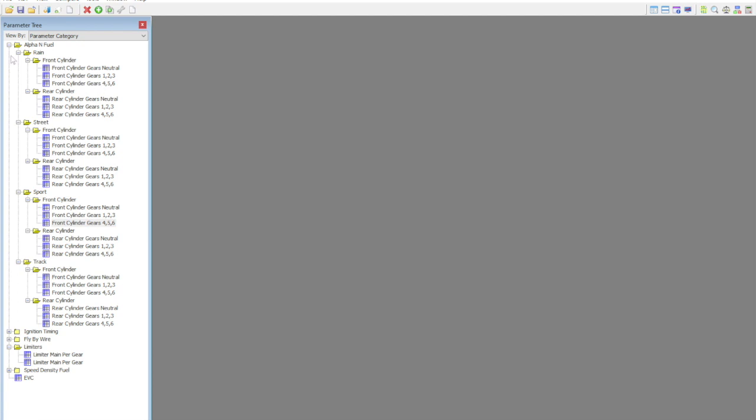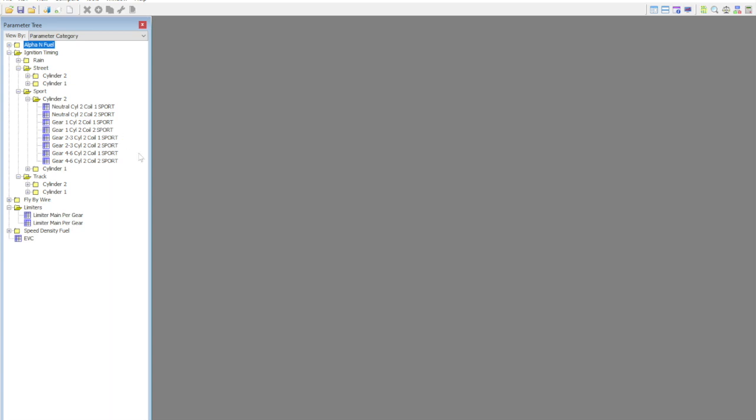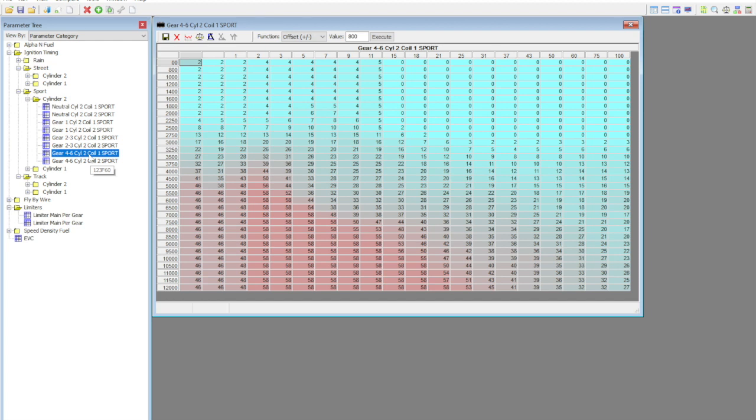Ignition timing now. These bikes love ignition timing to a degree. Like every engine, you can go too far and induce knock and hole pistons and do nasty stuff. Don't do that. The key for tuning ignition timing is to stop when the engine stops making power or when you start hearing audible knock. Fortunately for this engine, it'll stop making power a little bit before the time it starts to audibly knock. So you don't have to run right to the ragged edge and make that judgment call yourself.